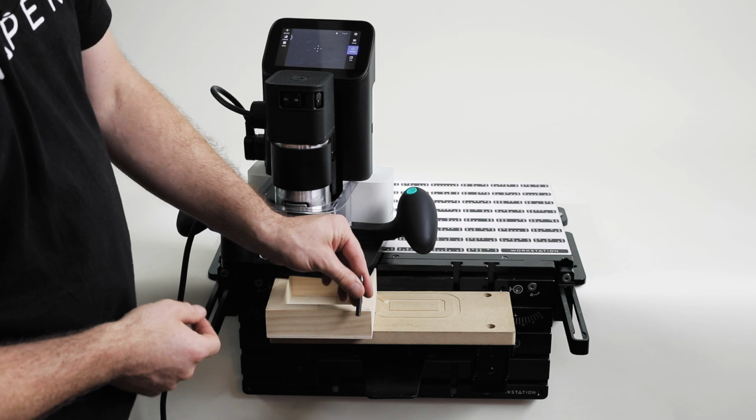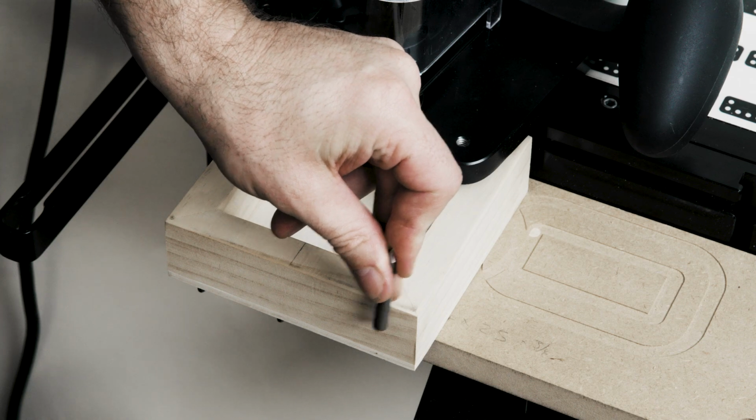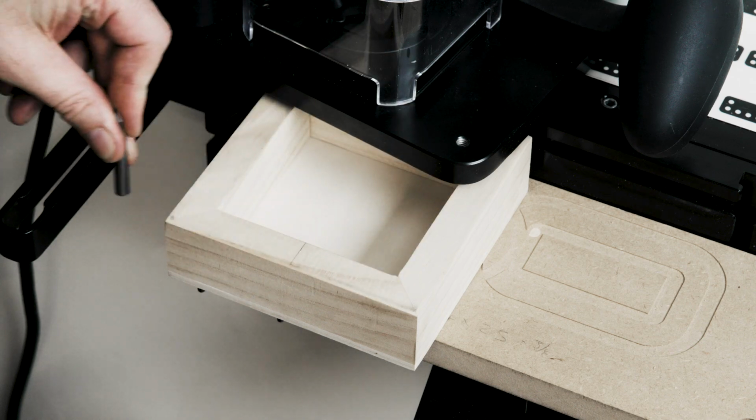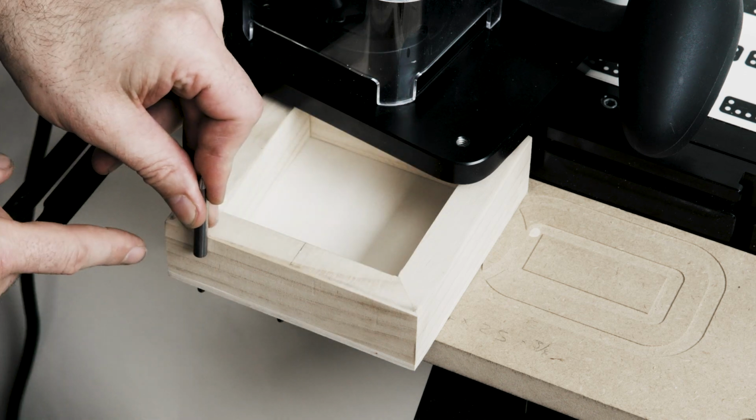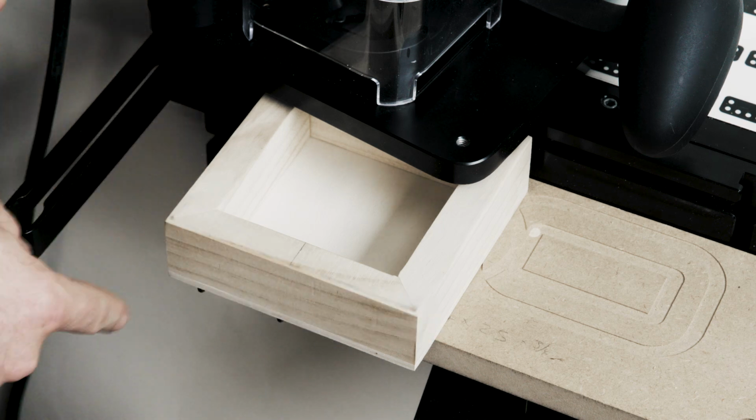So there are 4 different methods of gridding. There's the traditional physical probing method that we've seen. We'll walk you through that in a second. This is the standard approach to gridding that we're all familiar with. It's just lightly touching the probe against the edge to define two 90-degree surfaces.